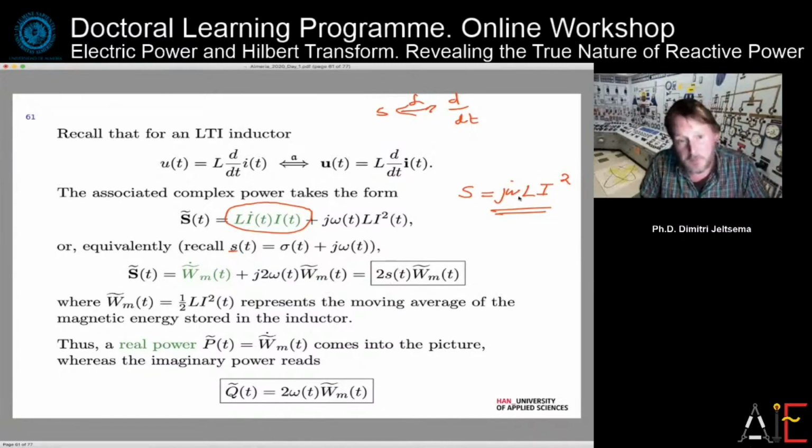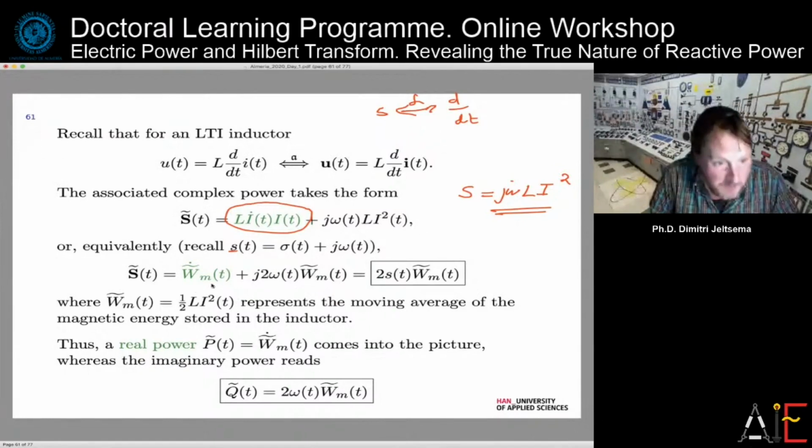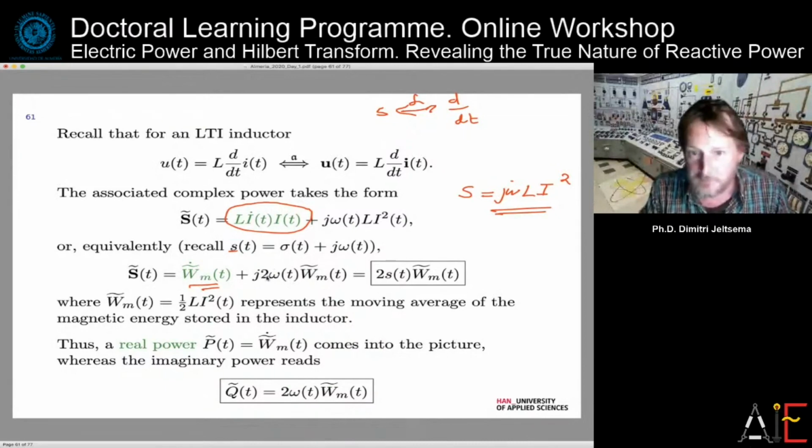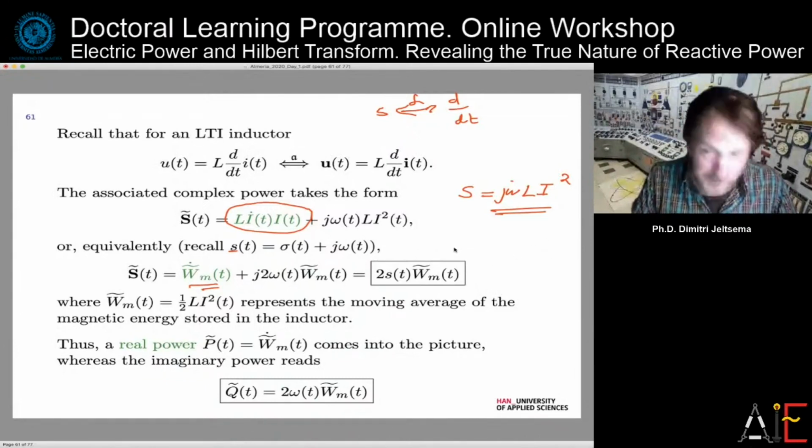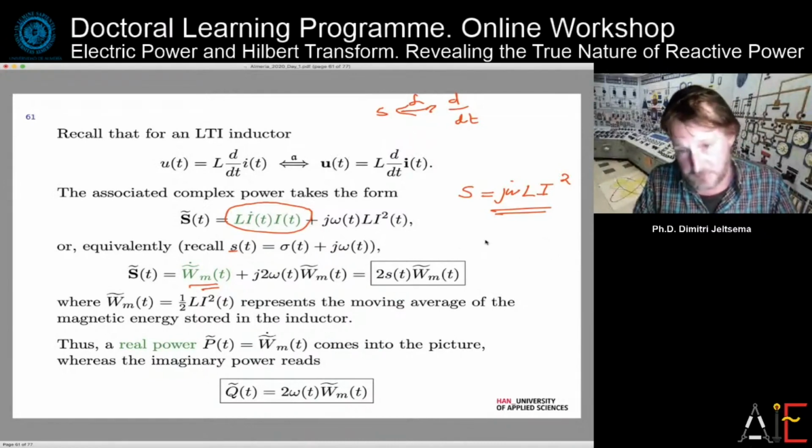But in contrast to the classical sinusoidal case, you now get this real part, and that's most probably why finding a proper, commonly accepted definition of reactive power is so utterly complicated. Because of a mix-up, a cloaking of imaginary and real parts. Usually, and that's also what Czarnecki is doing, for example, he defines reactive power as some kind of quadratic sum of all the imaginary contributions of your admittance, associated to each frequency.